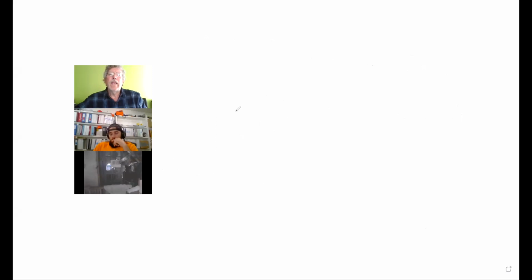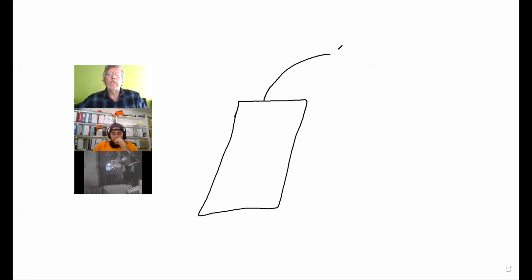So what we're saying is here's your service panel. And you're coming in from the utility. So this is going to be your utility lines here, transformer, all of that. All right. And we're coming into a main breaker and it's telling us we have 100 amps. So we've got a 100 amp breaker and we look at the label and it says that the bus bar rating for this unit is 100 amps.